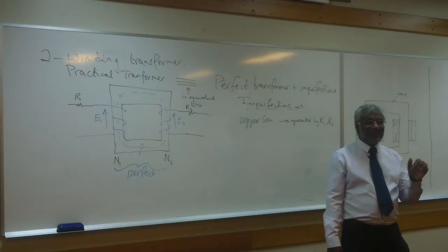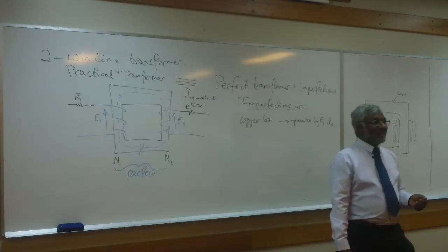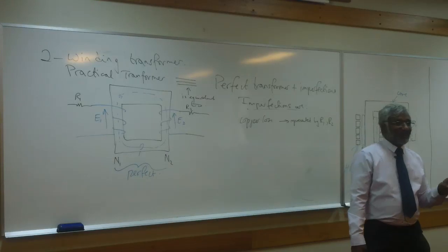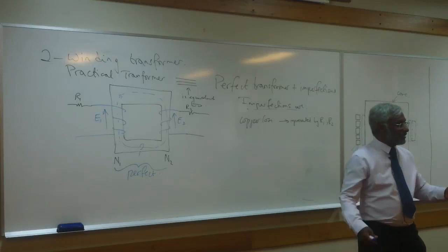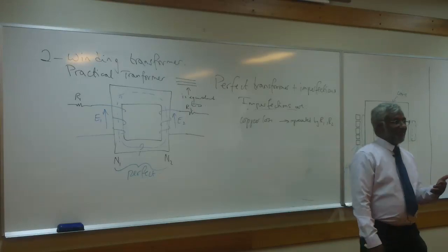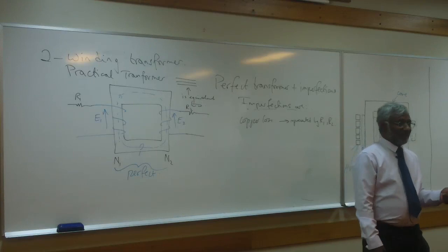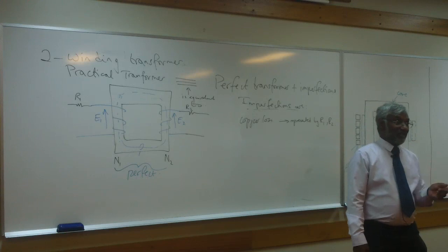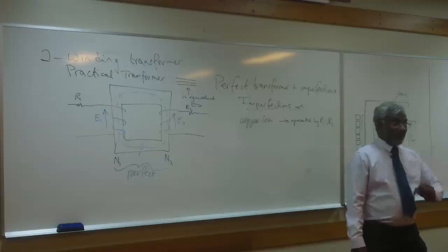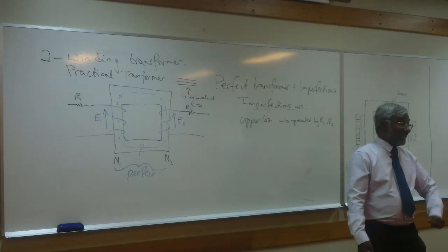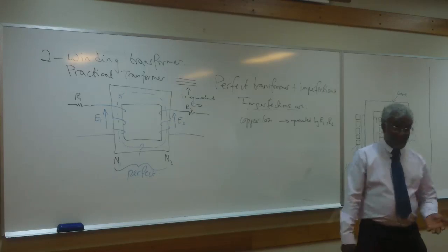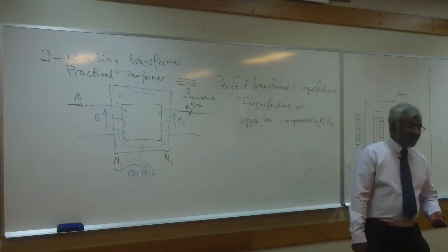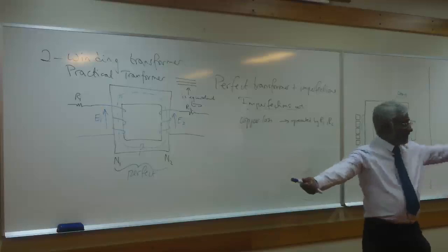1 kilo ohm? Yeah, about 1 kilo ohm. That would be not bad. And you know this because you know that 240 volts can kill, and you need somewhere tens of milliamps to kill. Somebody could die with 50 milliamps. So if 240 volts can kill, then 1 kilo ohm at 240 volts gives you 24 milliamps. So that's getting in the range. It can even be half a kilo ohm, especially if you touch with this hand and that hand.